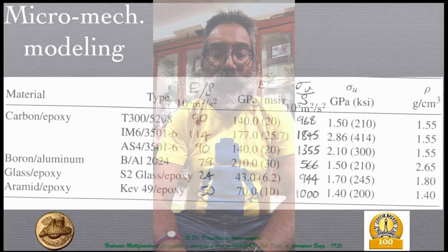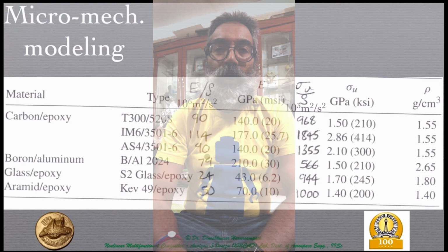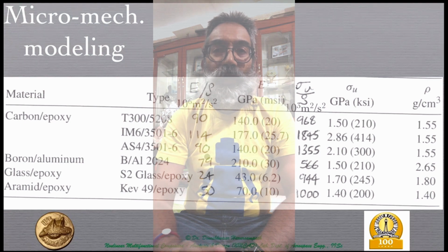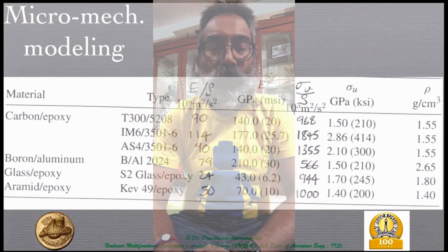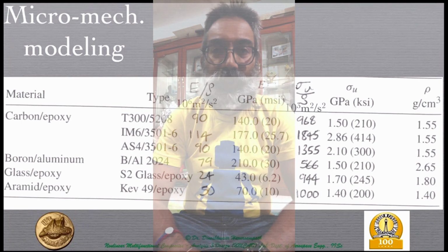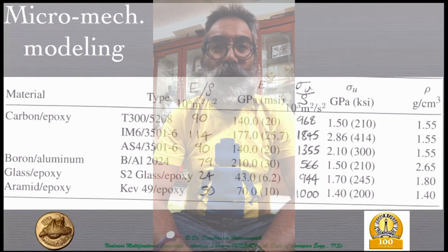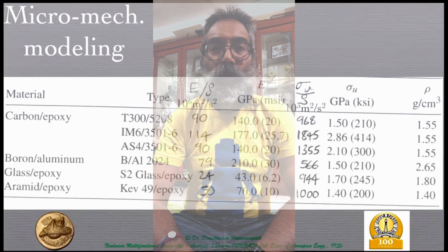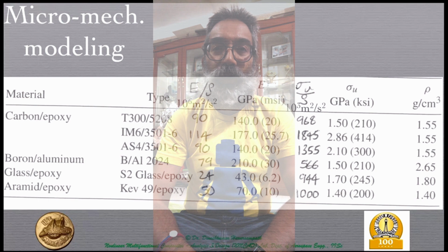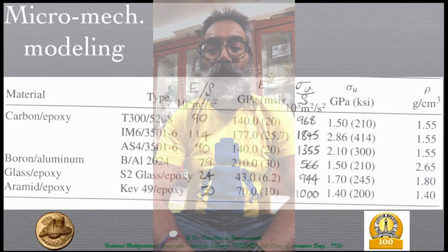That's important in actually determining these values. So let's assume that it's somewhere in that range that we talked about, typical for aerospace composites, which is a fiber volume fraction of 0.4 to 0.6, and therefore a matrix volume fraction of 0.6 to 0.4, assuming there are no other additives or voids.